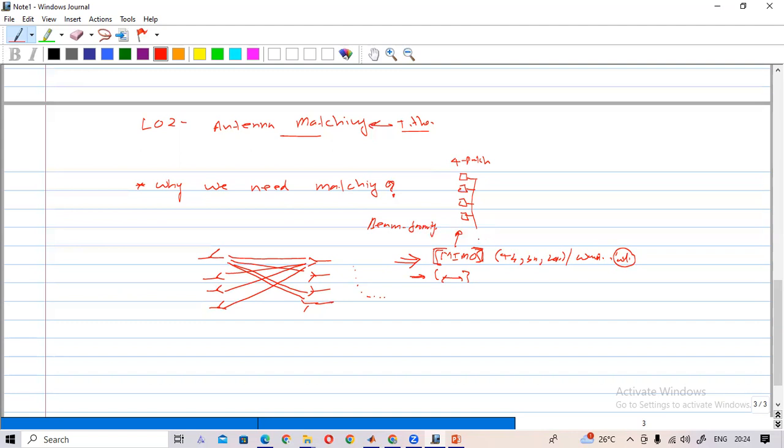So we have the antenna array, and all signals are combined or selected. Then the received signal will be taken. Then maybe there is a band pass filter, then an amplifier, then it goes to the demodulator to decode the signal, the decoder. Then maybe we send it to the speaker or something. So you can see that this kind of path is there, and the signal is traveling from one component to another component.